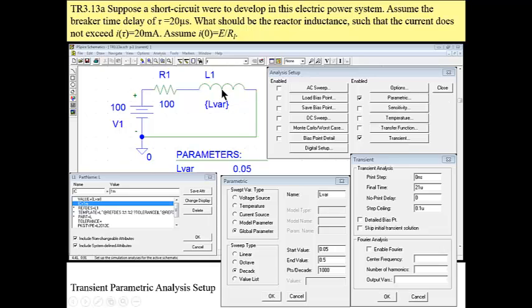In case of our coil that we are sizing, for the value of this coil we have to set a value as L var in brackets, and also, as we don't have a switch here any more, we have to set an initial condition of 1 milliamp calculated before. This is 100 volt divided by 100k connected here before.